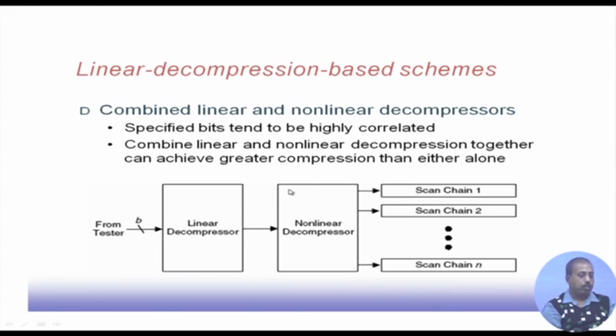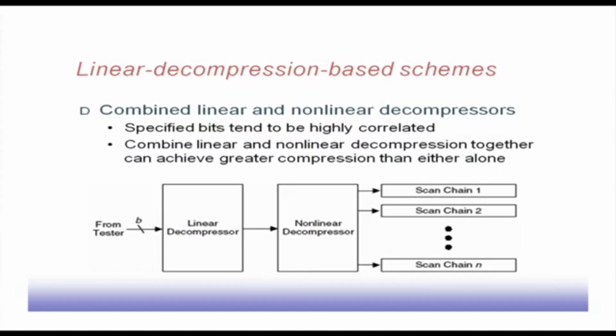There are combinations like linear and non-linear decompressions. Linear decompression is that XOR network based strategy, or maybe we can augment it with an LFSR, and after that we have got this nonlinear decompressor. Nonlinear decompression are the dictionary based approaches that we have seen. Now, if we combine these two together, then it can give rise to further compression.